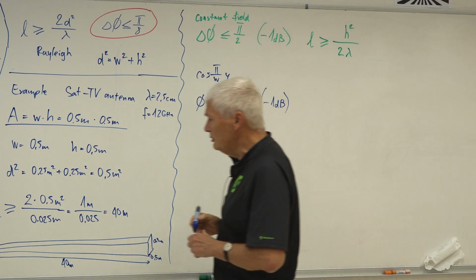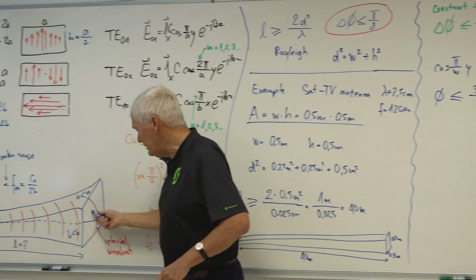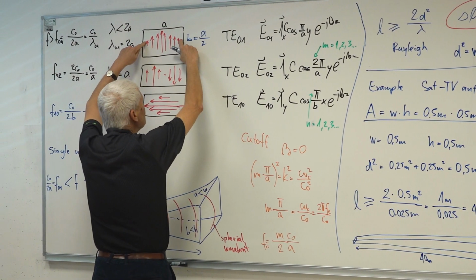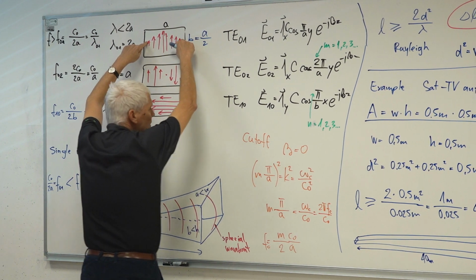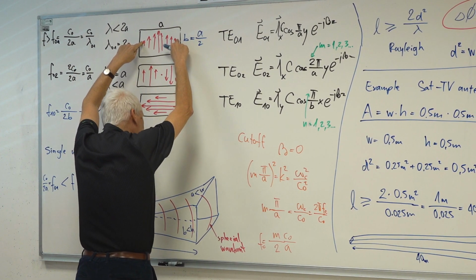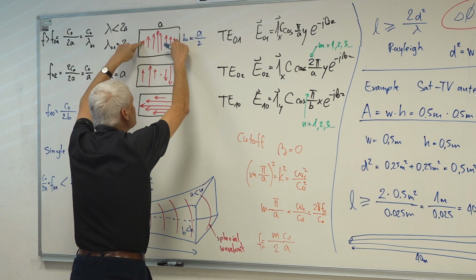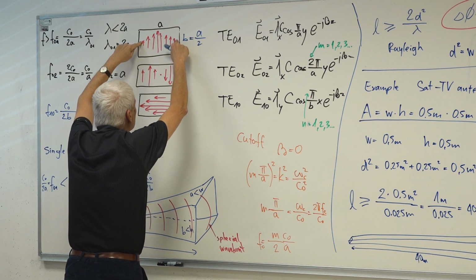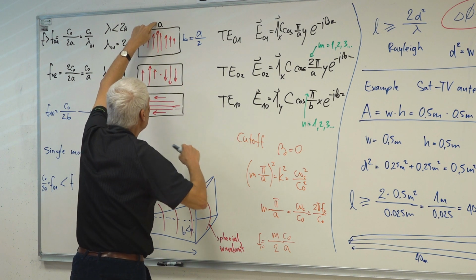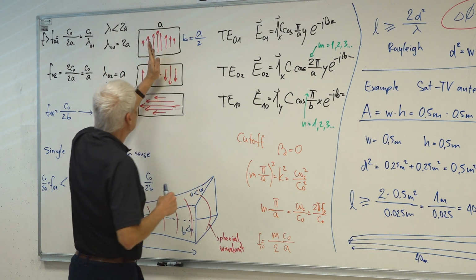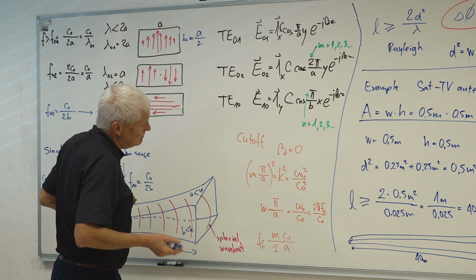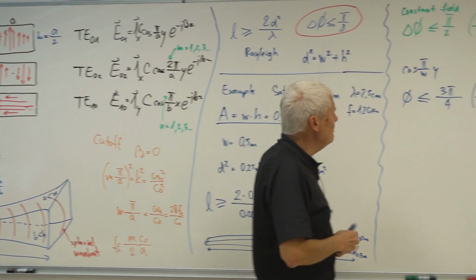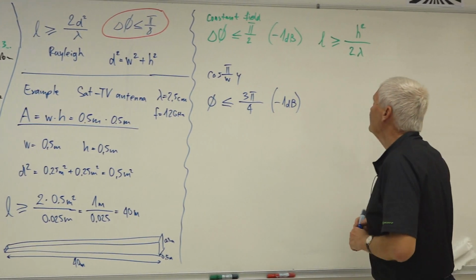You see, this distribution in the H-plane, you have very little field here, very little field here. So this small field doesn't really matter that it has a large phase error, because it's not going to count much in the final result, rather than this field here. While in the other dimension, in the E-plane, I have a constant field, and in the E-plane, every single point counts the same. So here I may have a less strict requirement for the phase error.